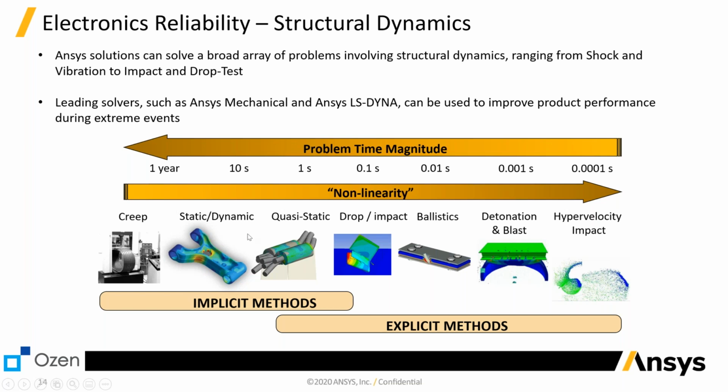So then you can use ANSYS Mechanical because ANSYS Mechanical has really good creep formulations. There are 13 different creep formulations, and in addition to that, there are viscoplasticity formulations in ANSYS Mechanical. Again, viscoplasticity and creep take place over long periods of time.